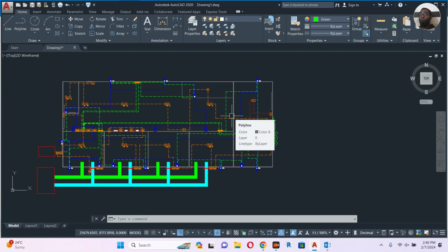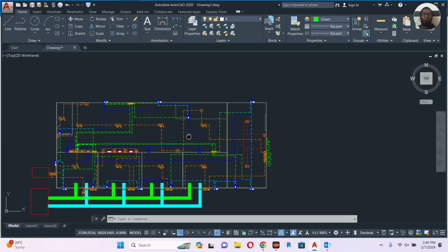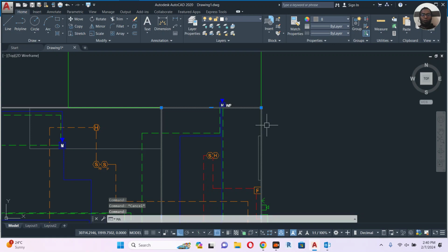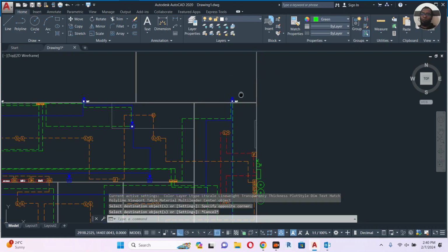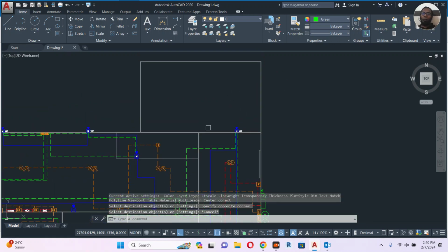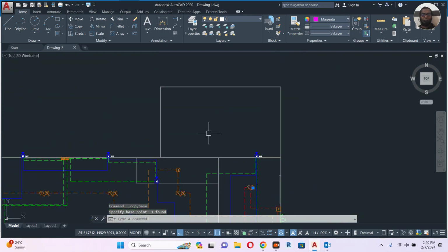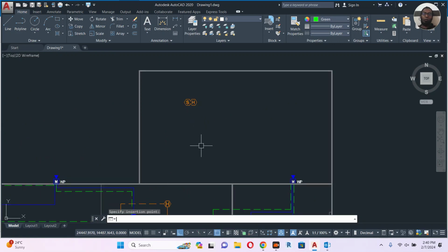We have pump room. Okay. So pump room, let's say we will draw one pump room here. I am not going to draw the pump room, but I will explain the concept. The pump room itself, we need some detectors. So we can put multi-sensor to sense heat and smoke together. So 1, 2. It depends how much coverage you need.